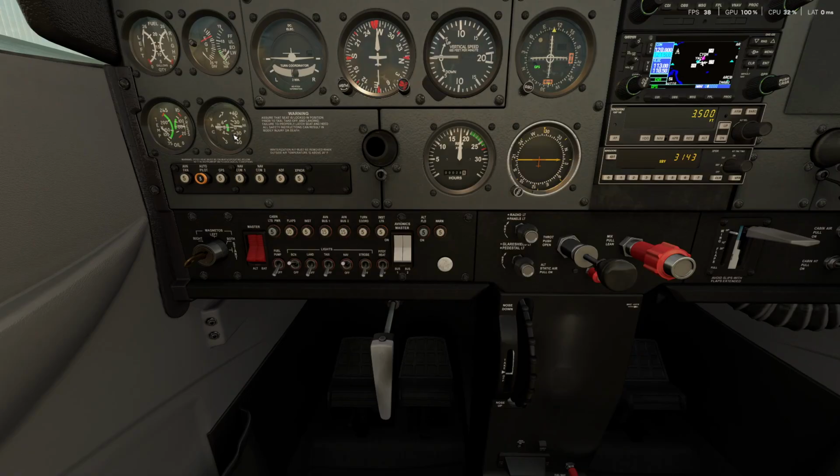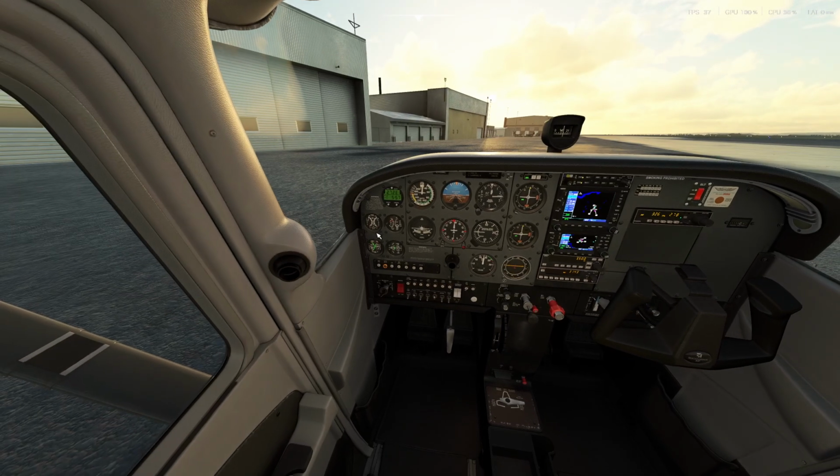What I'm going to do is load the electrical system with the manual lights. We're going to see that there should not be a discharge in the electrical system. Great, so it doesn't change, that's good. Go ahead and turn those over. Another thing I like to do is turn the alternator off. And what we're going to see is the ammeter is going to show a discharge, like this. Turn it back around, so that means the alternator is working.